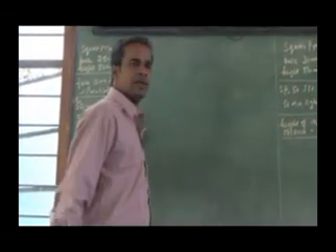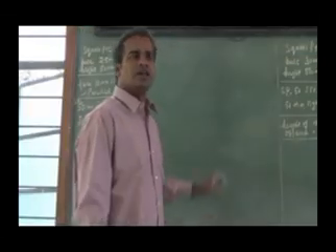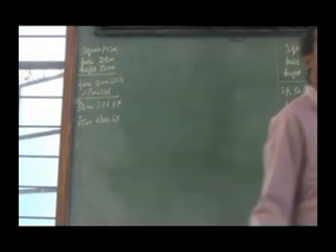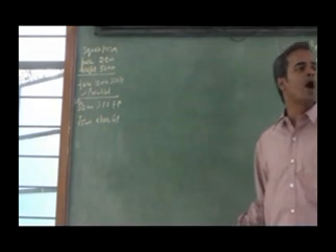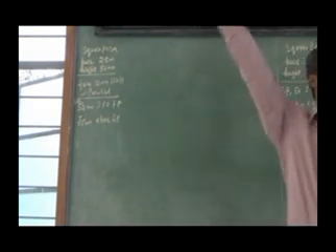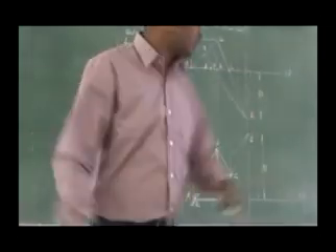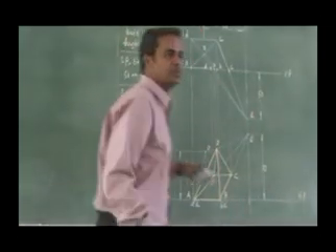Draw the layout quickly. Try to get the perspective. Listen here. Since a small portion is coming in front of the picture plane, try not to draw the ground plane to the bottom. Why? If a small portion is in front, that in-front portion will be bigger in size in your perspective. So leave some gap for the enlarged perspective.